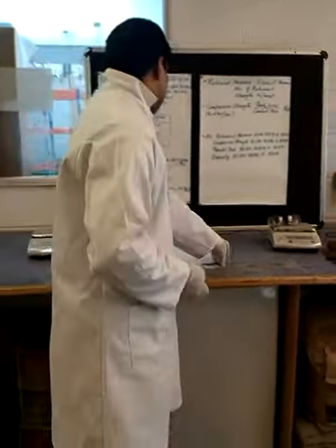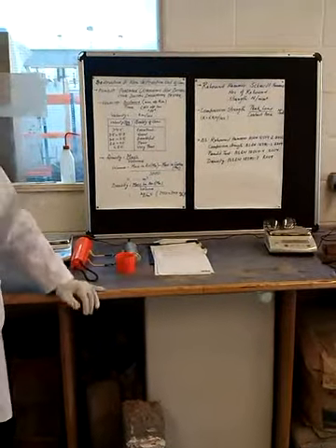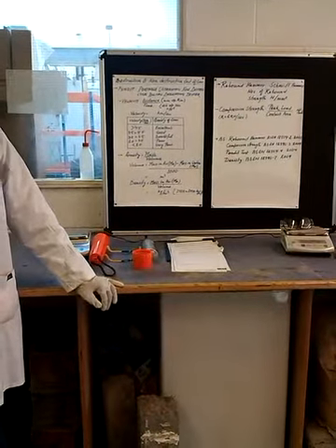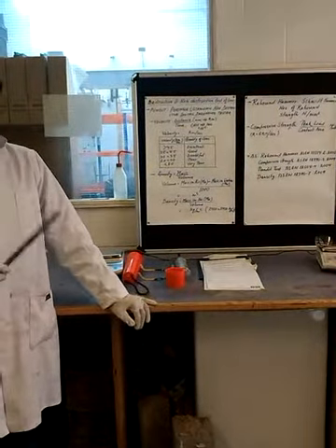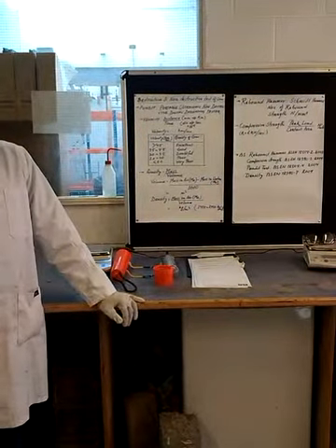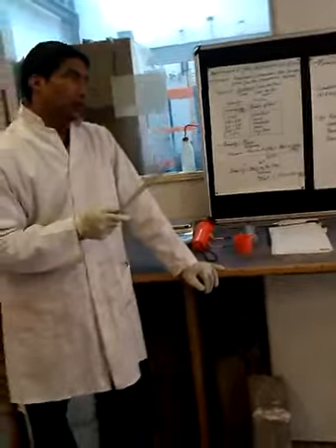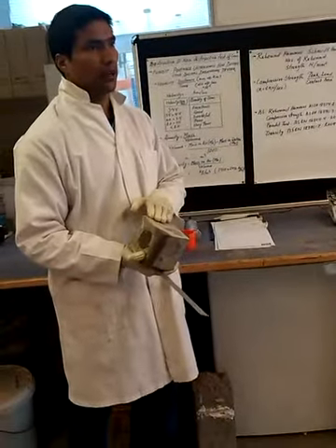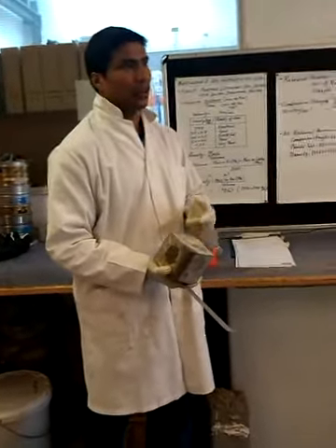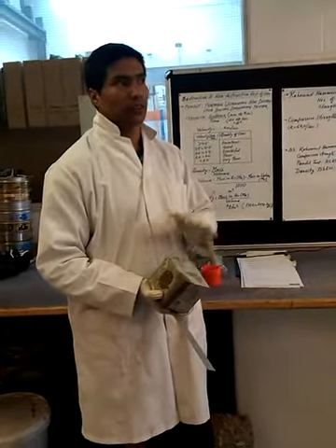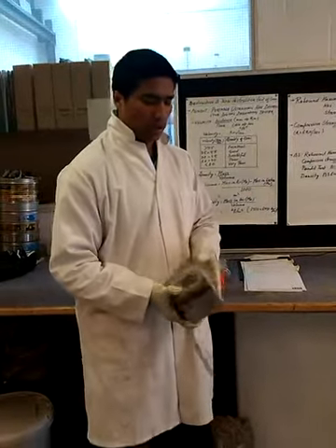Now the other thing is density. The strength of the concrete depends upon the material properties, water, that we are telling since the beginning of the classes, water cement ratio, material properties, and density of the material as well, or the density of the concrete. So if you don't have proper vibration when you are doing the casting of the concrete, you may not have the proper density of the concrete. You may get some voids inside it, right? If you don't have the good density of the concrete, you will not get the target strength of the concrete. Okay, so we will check